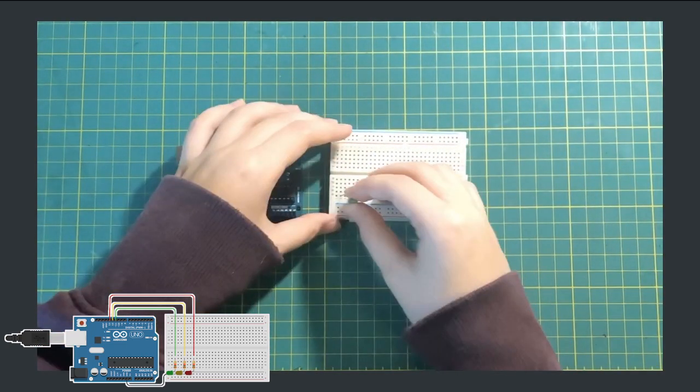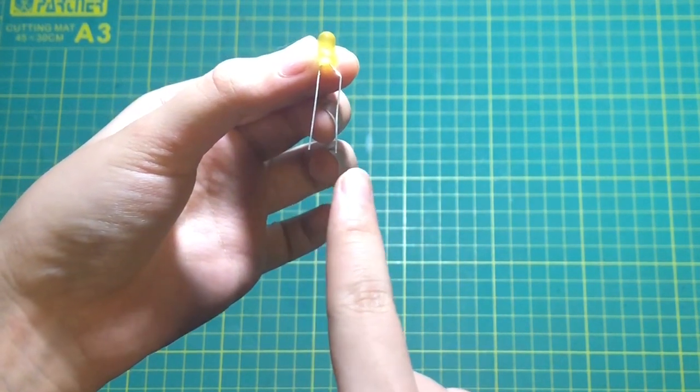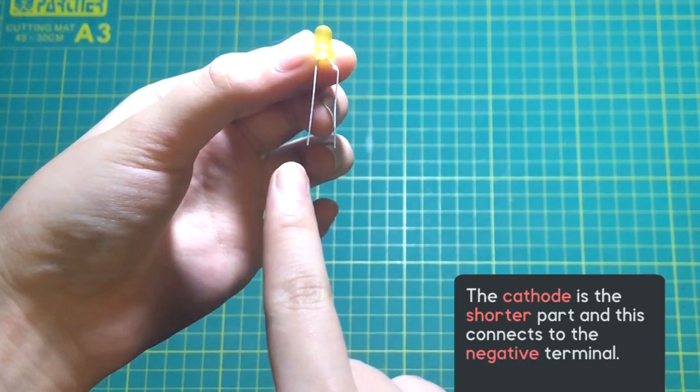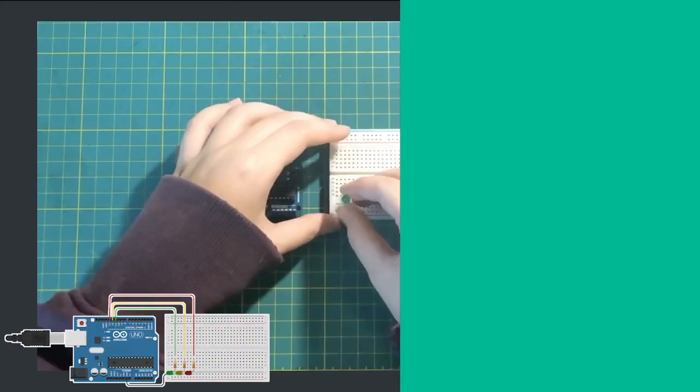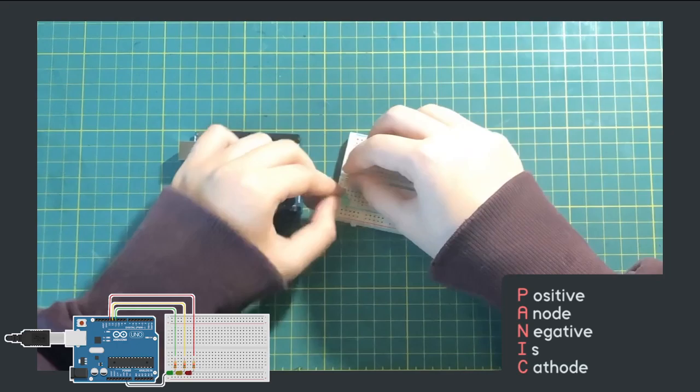One last thing before we get started. It's important to differentiate the LED's cathode and anode. The anode is the longer part, and this always connects to the positive terminal, while the cathode is the shorter part, and this connects to the negative terminal. Just remember panic. Positive anode, negative is cathode.